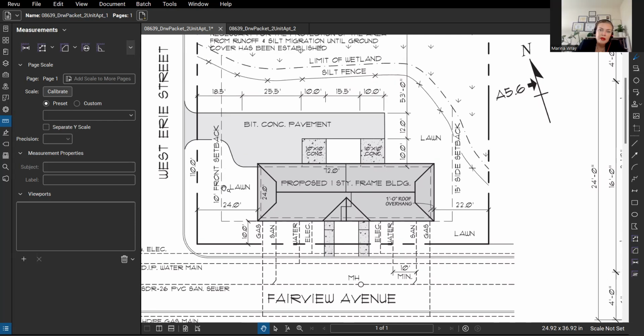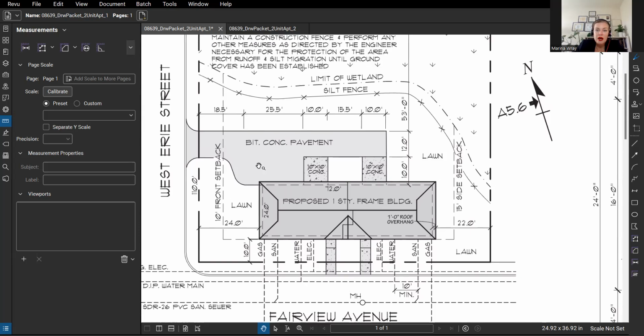Sorry, no, the 22 and 24, that's the distance between the property line and the building. I apologize. So here we see the 10-foot front setback, and this is stated here, and the 15-foot side setback. So these are actually the setbacks. They dictate the buildable lot. This is where we can build. This is where we can place the buildings. These are kind of like the limits.